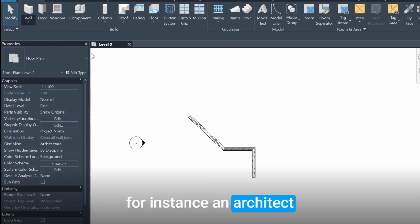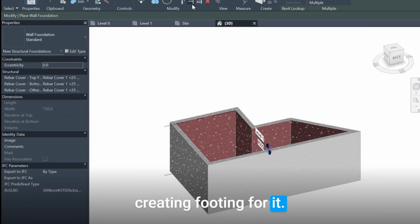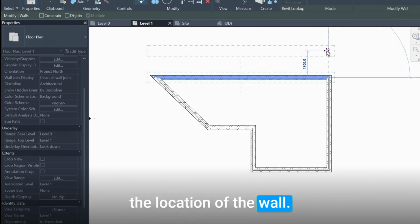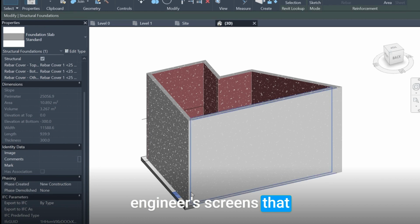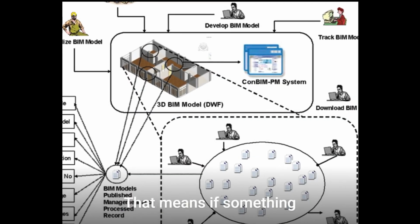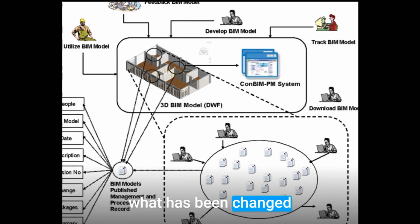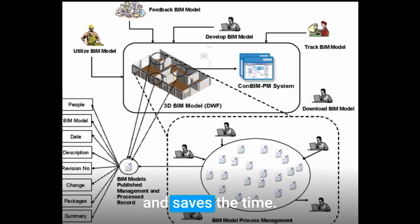For instance, an architect creating a wall into a central BIM model and a structural engineer creating footing for it. Suddenly, architect realized it is in the wrong position and decided to change the location of the wall. Immediately, a message will pop up to the structural engineer's screen that location of the element has been changed. Wow, means each stakeholder will be notified if there will be any change in the main project file. That means if something has been changed, it will be recorded what has been changed, by whom and when. This level is most likely to reduce the errors and saves the time.